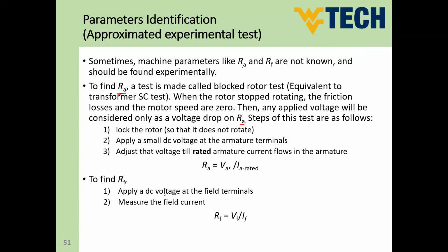Take care that when you take these results, you have to wait a few seconds. Actually, it depends on the motor time constant. If the motor is a huge motor, the time constant is going to be relatively high. If it is a small motor, the time constant is going to be relatively small. So why should you wait?